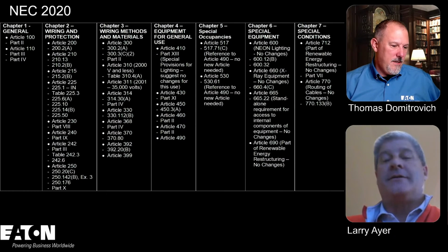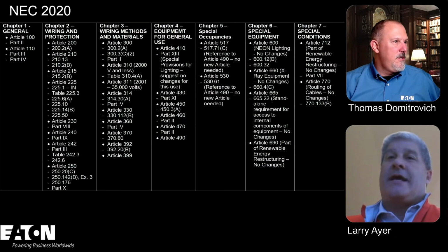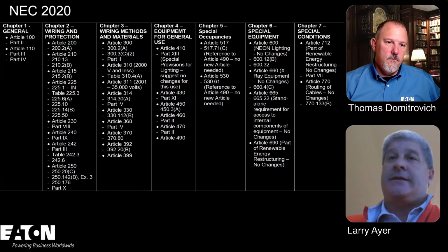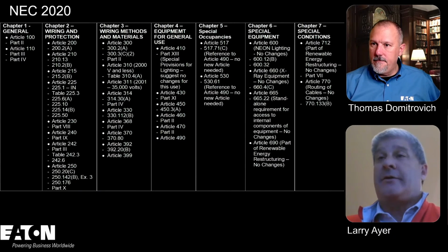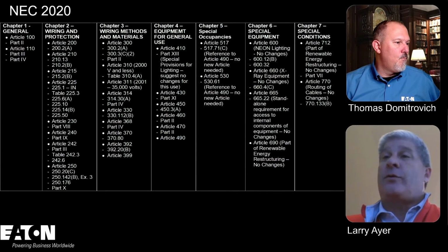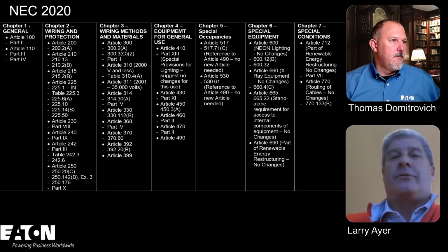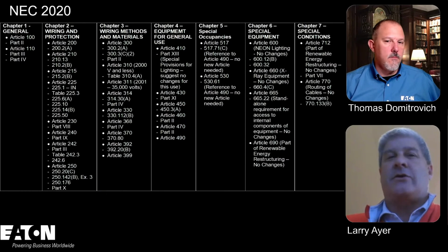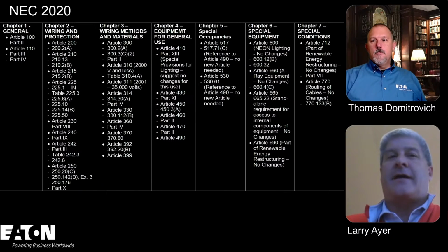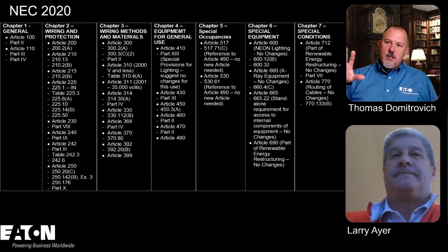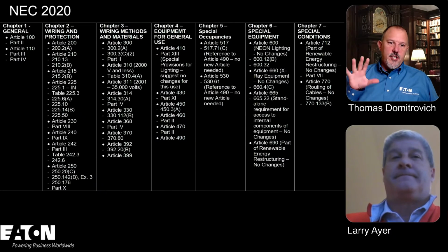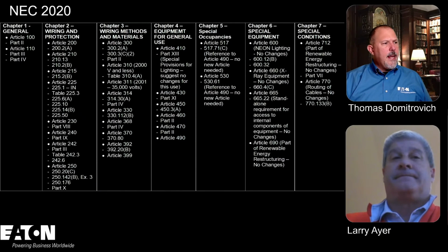Yeah, so now the direct burial is the fact that we have some requirements in the NEC to bury 35 kV cables at 6 inches, and that just doesn't seem accurate. The NESC is at 42 inches. And so we have some technical things that just don't fit, and we've got to figure out how to make those better. Right. So this is how the National Electrical Code is laid out right now in the different chapters.